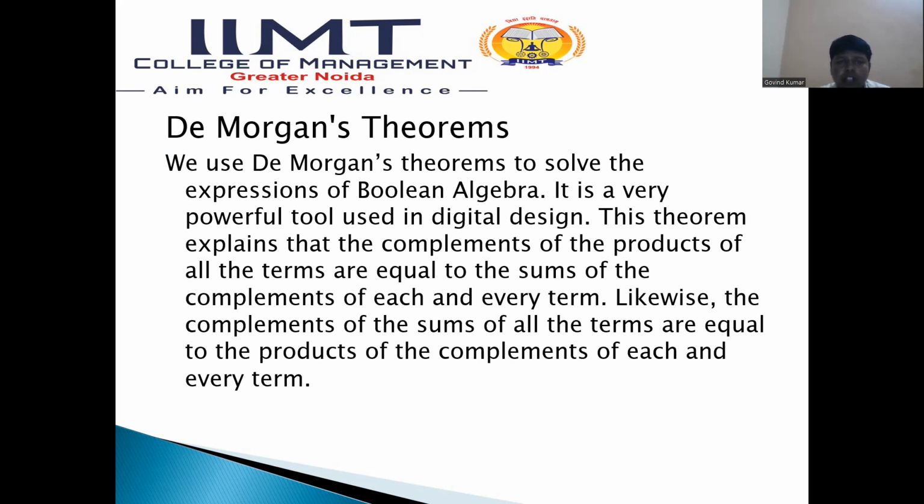We use De Morgan's theorems to solve expressions of Boolean algebra, and they are important tools used in digital design, computer architecture design, and digital communication design. The theorem states that the complement of the product of all terms is equal to the sum of the complements of each term. Likewise, the complement of the sum of all terms is equal to the product of the complements of each term.